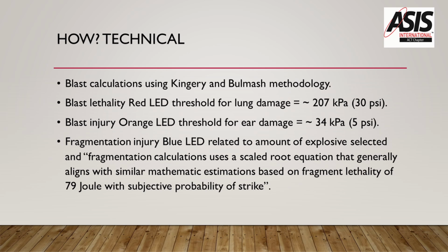For those that are interested in the technical aspects, all the calculations are based on the Kingery and Bulmash methodology, which is most famously recognised as the basis for CONWEP, which is the old but very well used and heavily validated blast assessment methodology for doing calculations for charge weights over distance and pressures.